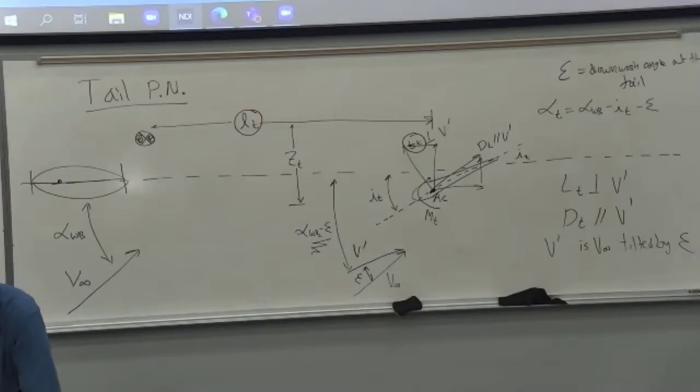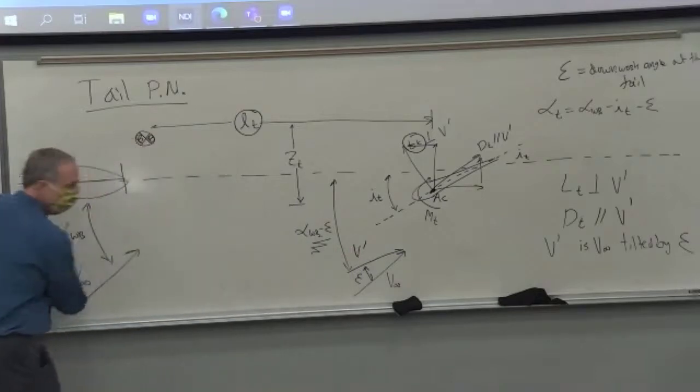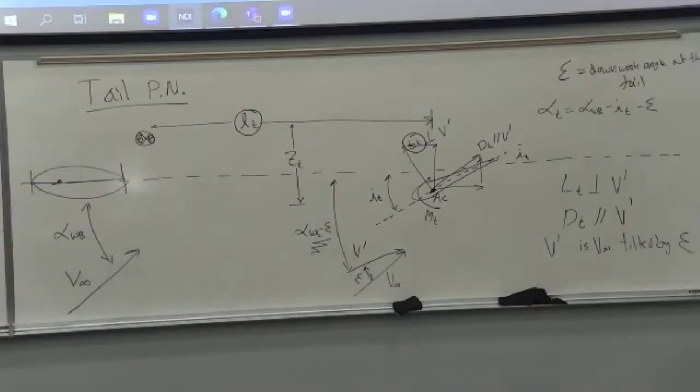With the wing, the flow lines of the wing actually affect the flow. Yeah, that's what we're doing with that downwash. Technically, this flow might be slightly slower than this because you have the wake. You can take that into account as well with Q infinity, but typically we don't. But the downwash angle does affect the flow.